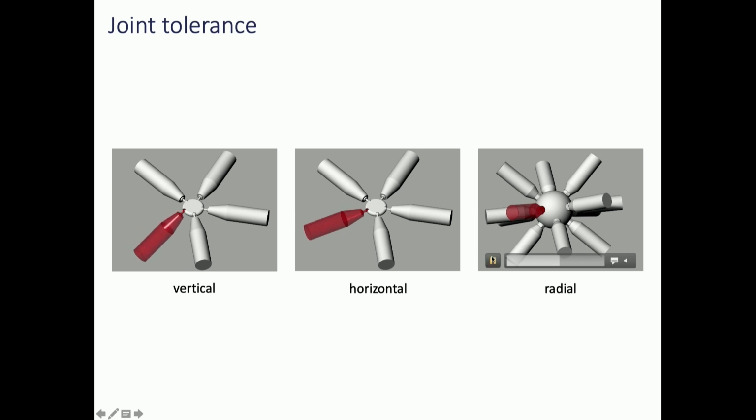Theoretically. Anyway, so different joint designs allow for different degrees of tolerance. And this can be either because the design itself allows the members that connect the joint to move on different planes, either vertical or horizontal, or because the fabrication manufacturing equipment isn't 100% precise. I mean, even with a robotic arm, you do have a tolerance of 0.01 degree within a lifespan of 2 years, or even in fabrication.